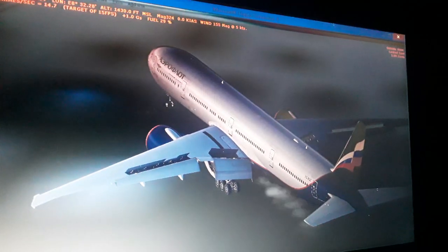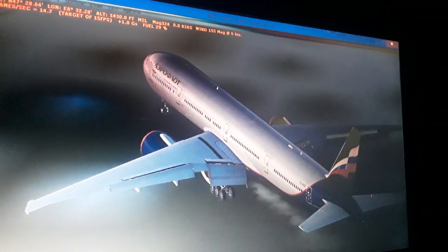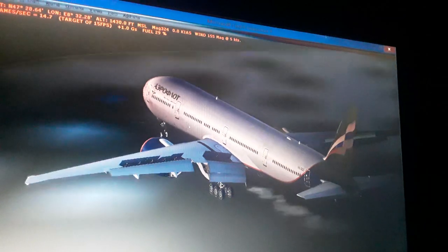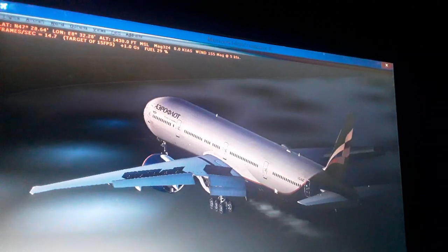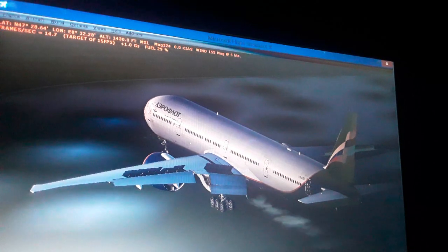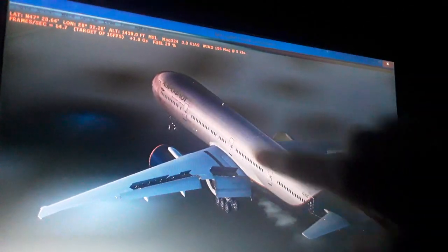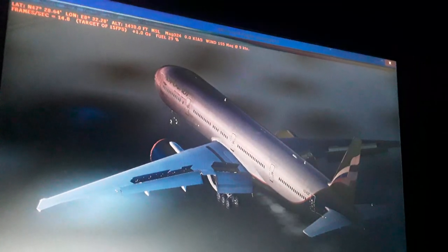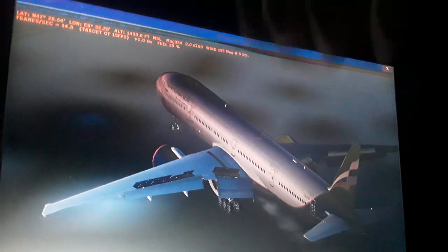You have also the flight controls that move around, so you can make bank rolls using the ailerons and the spoilers, so you can climb and descend using the air mass deflection, and also make steering of the airplane left and right. So you have the vectors from this side and also from this side, the longitudinal and the lateral and the vertical axis of motion of the airplane.